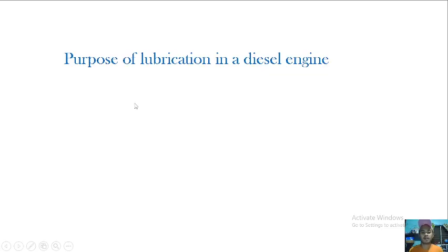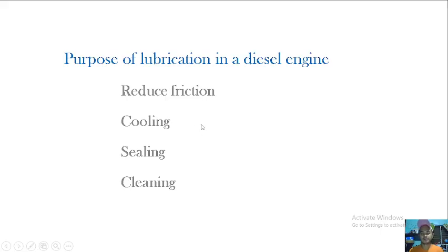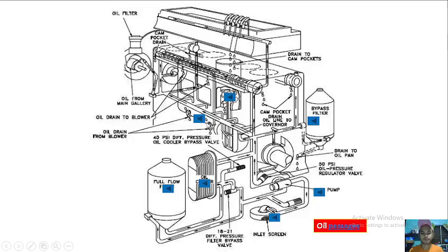The main purpose of lubrication in a diesel engine is to reduce friction. It also cools down by removing or absorbing some heat from the moving parts, so it also serves as cooling, sealing, and cleaning. So this is our sample engine, and we will be focusing on the lube oil system.